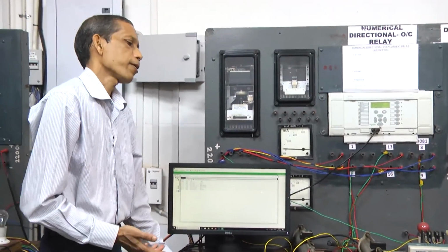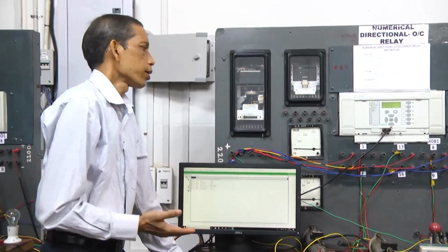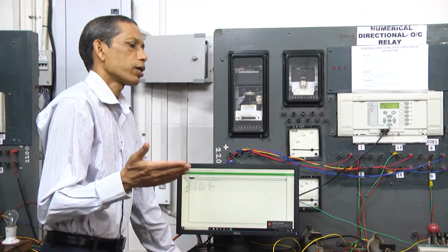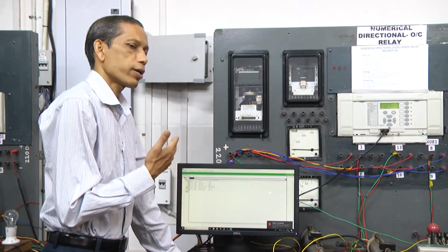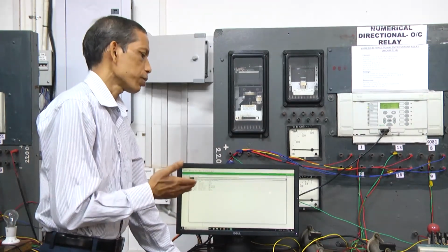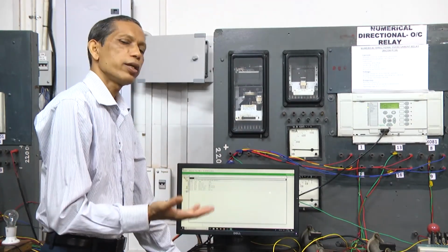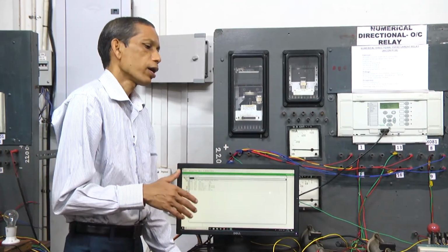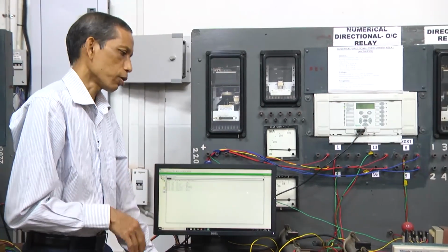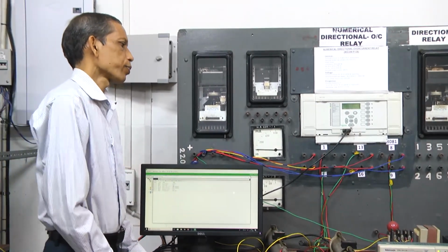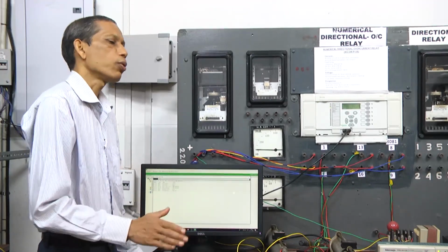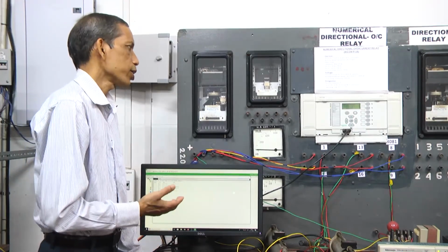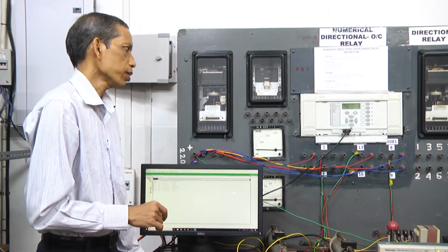So, we verify at different points that the relay is following what is expected for a forward fault in the region of gamma to beta, and with current exceeding the corresponding pickup setting of 1.5 ampere, the relay is operating. In the reverse fault case, beyond that set angle, it is not operating. So, for this relay we took several observations throughout, for different situations and different settings, and we find that the corresponding directional overcurrent relay is performing correctly.